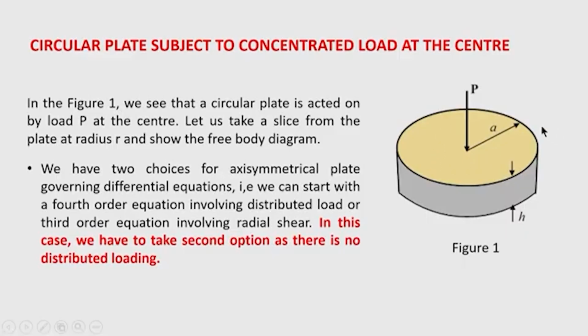One equation is the one relating the fourth derivative of deflection to the distributed load, and the second one is relating the shear forces to the externally applied load. Since there is no distributed load, the second option will be better in this case, because in the absence of distributed load, the forcing function of the differential equation cannot be written here.